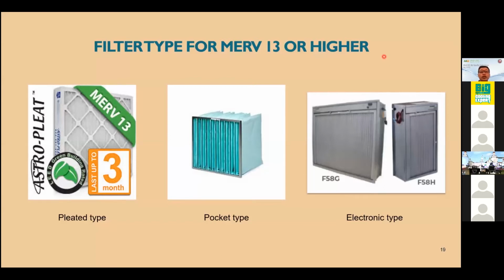So if you were to include a pocket filter, which has a higher static pressure loss or drop, then I believe you have to look into your fan, because the fan does not have the capability to move the air since the filter is too high efficiency. So the resistance for the air to pass through the filter is higher, so you have a static issue.